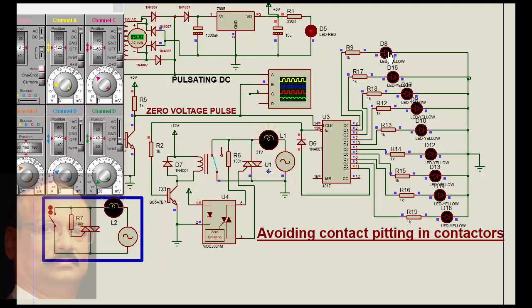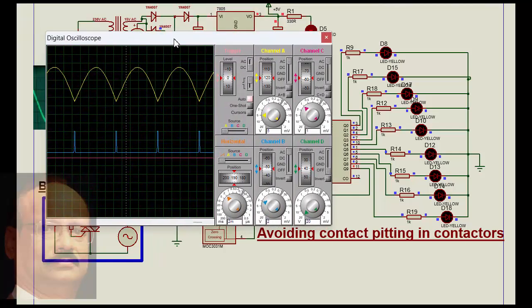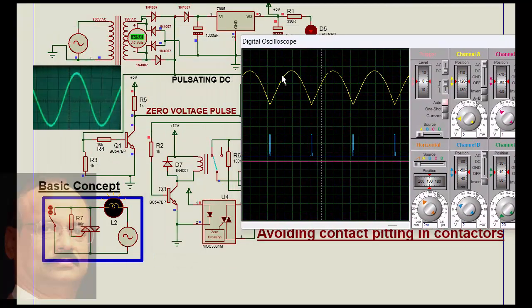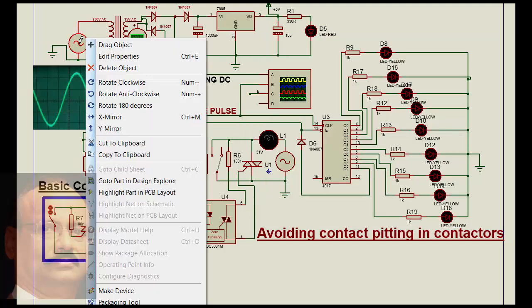It has switched on from here to here, and then the relay has switched on to this side, making the contact in parallel. Now if you look at this waveform, we get pulsating DC, and these are the zero voltage pulses. We need the zero voltage pulses for switching at the zero voltage.